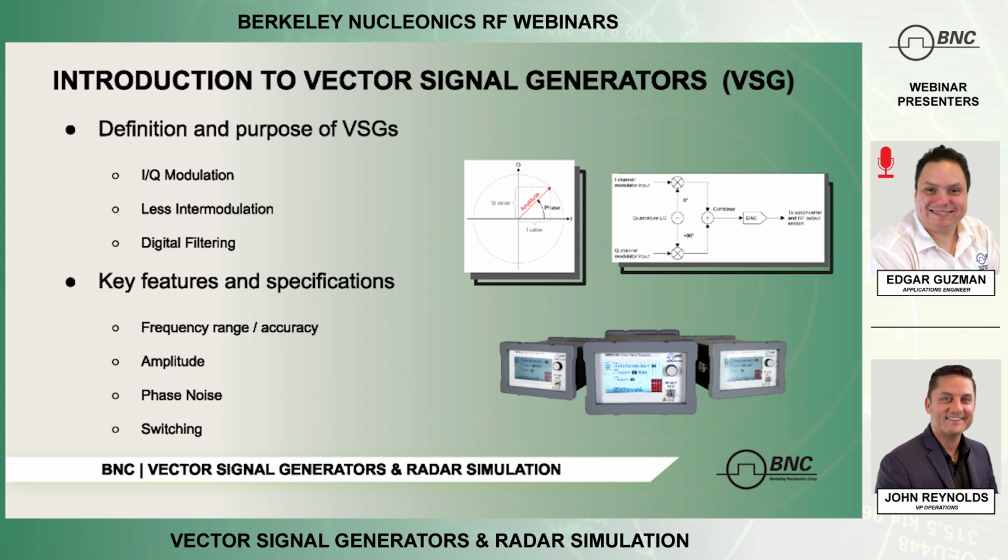So the main features of a vector signal generator, or pretty much any RF or microwave signal generator, usually boil down to frequency range and accuracy, the amplitude or the power level which you're capable of outputting, and even the accuracy of that, the phase noise of the actual signal, as well as the switching speeds.